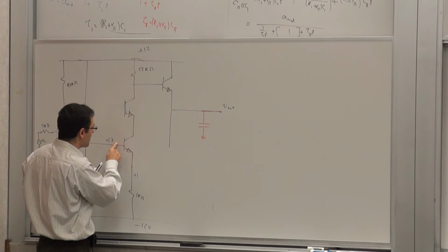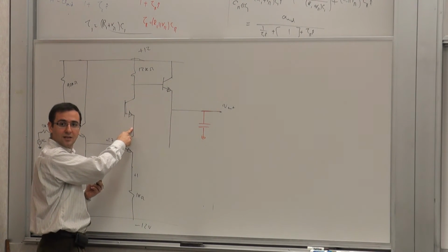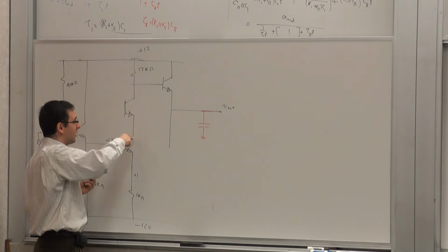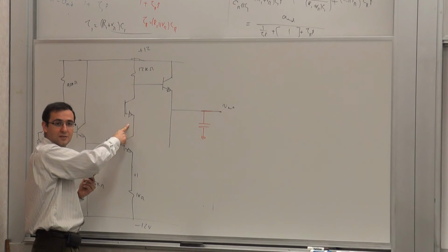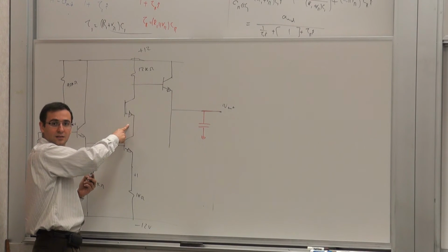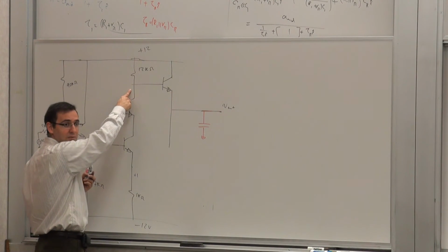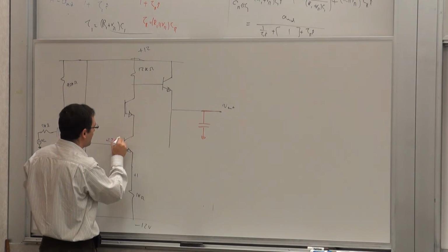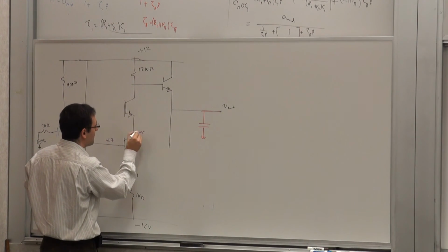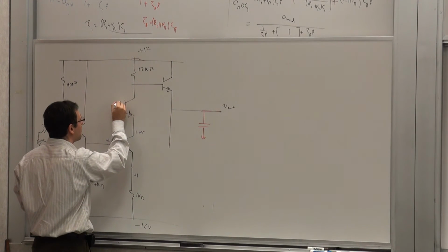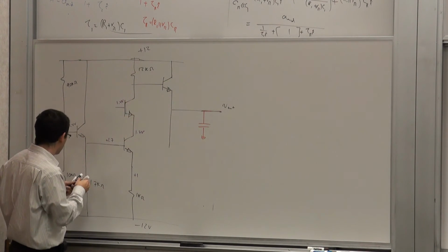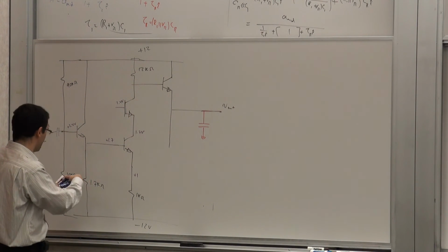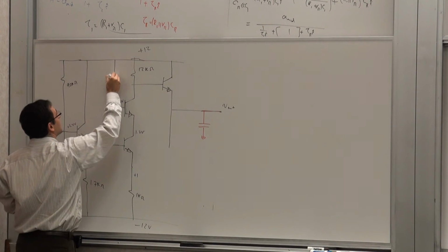So I don't have much gain from here to there. So there's no risk of this swinging a lot and going to saturation. The gain from here to there is 1. The gain is happening really from here to there, the common bits, which I still have to bias. But if I put this at 1.7, that's fine, and then that puts this base voltage at 2.4 volts too. So I have to have another 2.4, so I would use the same kind of resistors.